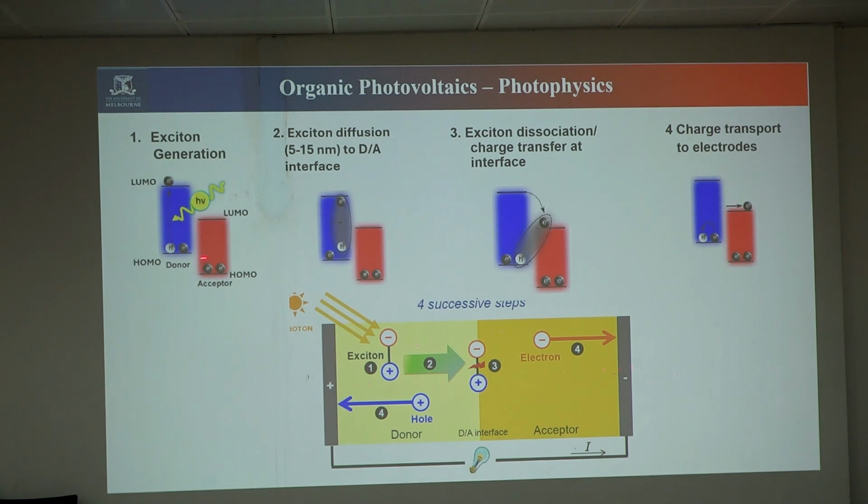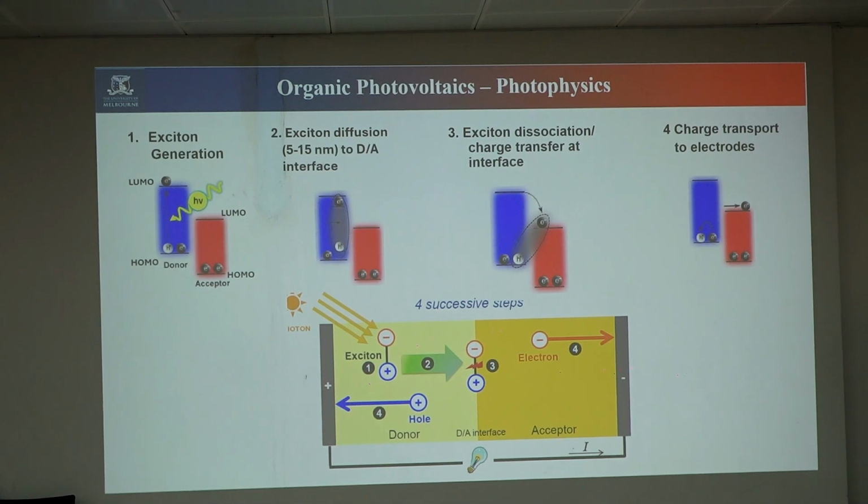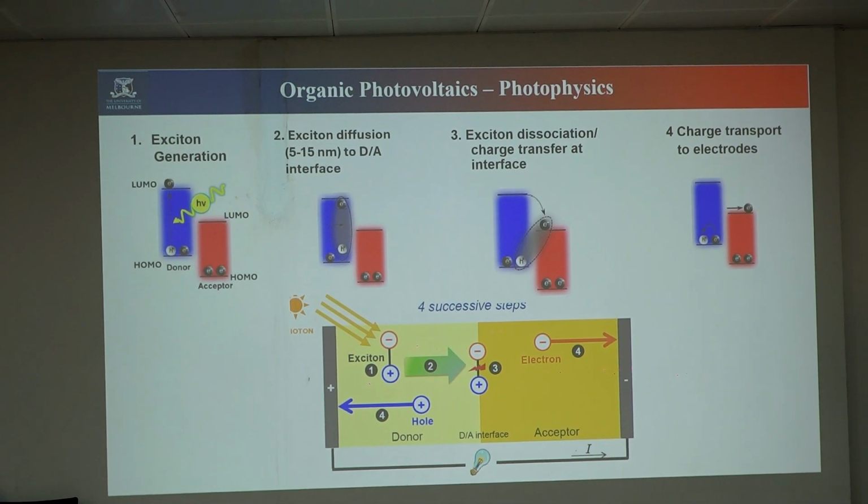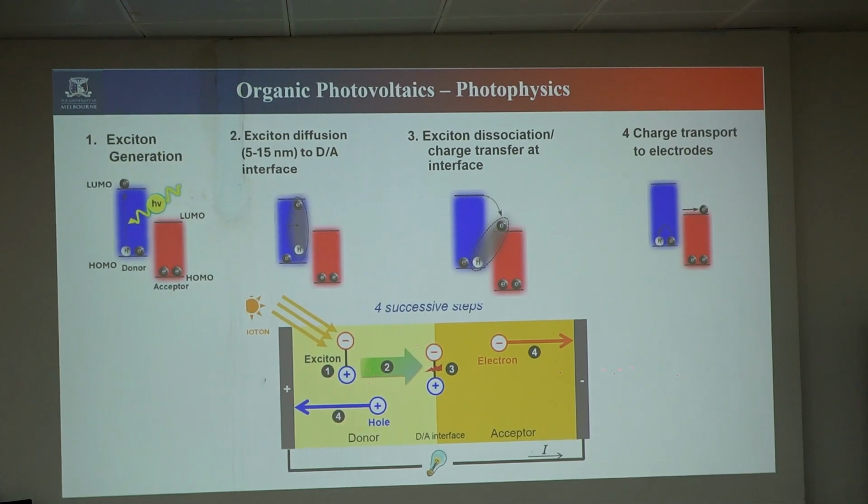Because it is an exciton, you need to understand that exciton means bound holes and electron. That's the meaning. So the main difference between the organic solar cell and silicon is that this bound distance is very high in silicon, so it can easily separate out. Here it is very close. That's why we need to have this much offset to separate out. In silicon we need not worry about this because everything is the same. The offset is needed because this charge is so bound. We have to give an energy step difference to separate it out.